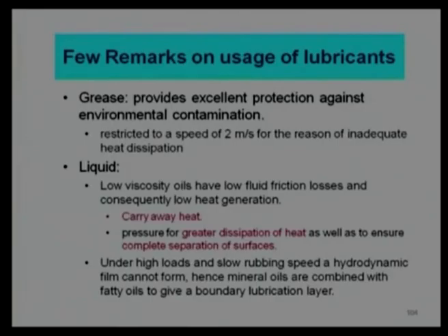In those situations, again the low viscosity lubricant will be preferred, because the high viscosity will give more resistance to pumping, and more resistance to pumping means there will be more power consumption. So, power loss will increase, and the cost will increase.